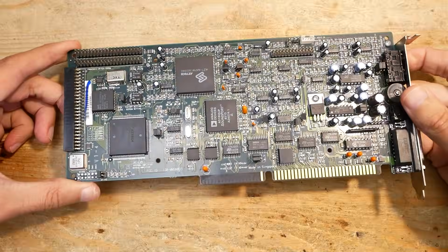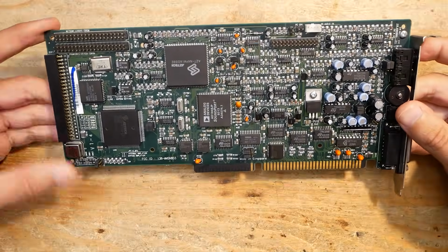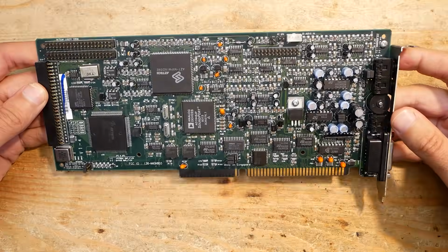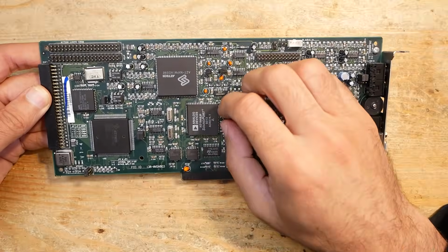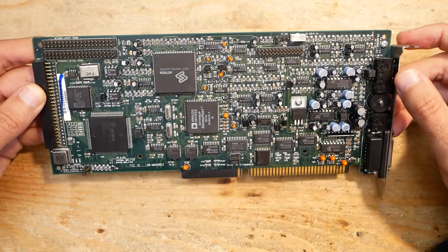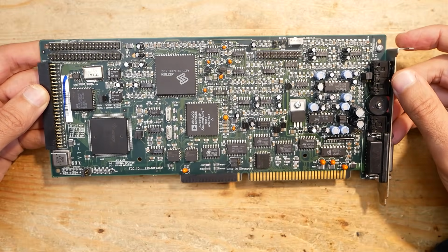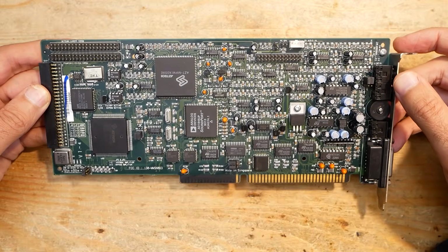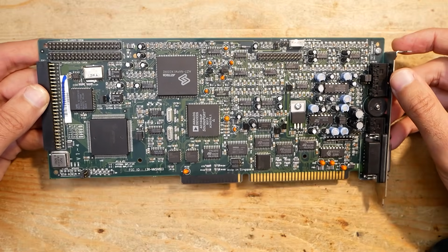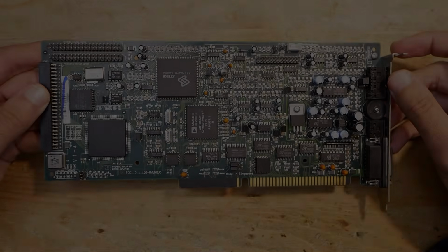So my verdict is that this card is beyond a repair, mostly because the parts would be so hard to find. My assumption is that something has shorted the regulator and probably 9 volts from the output found its way through the ground into various parts of the card. What has potentially damaged multiple ICs? What a bummer, but maybe we will have more luck with another one.